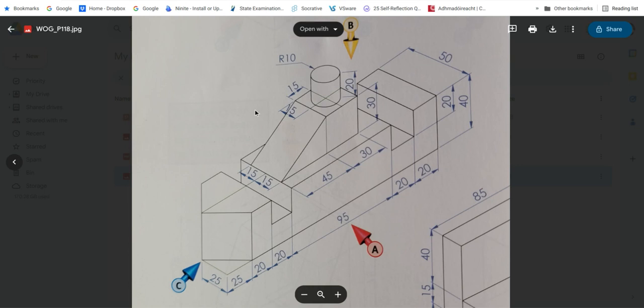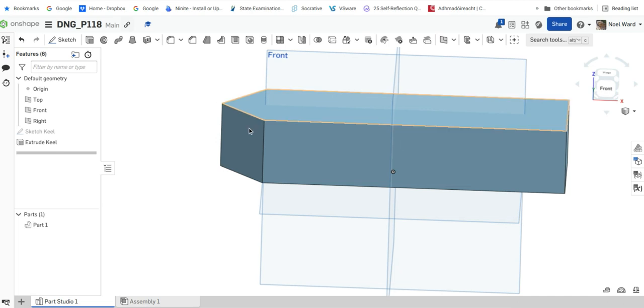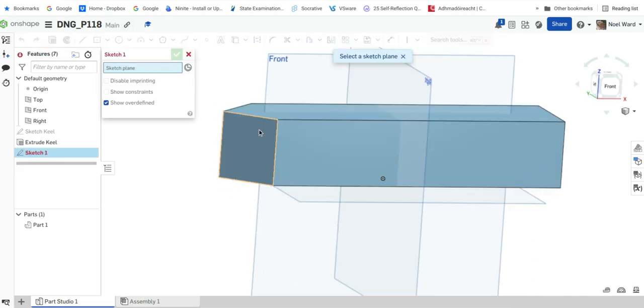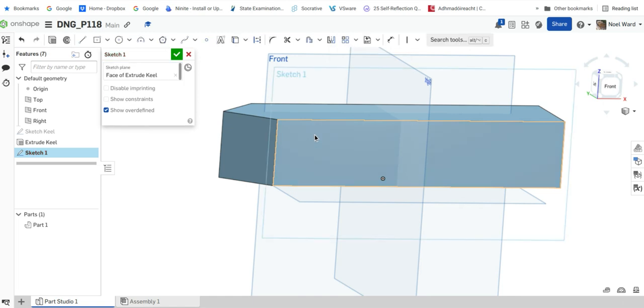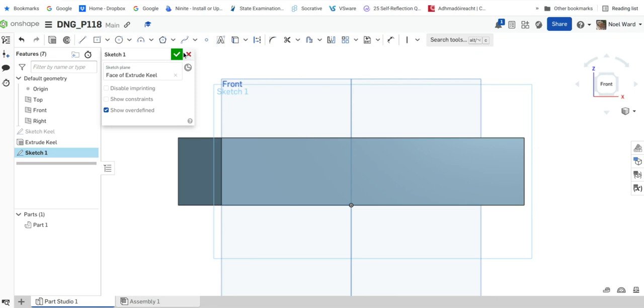Take a look. Then there's a couple of openings here. Simple dimensions, 20 in, and then it's the same 20 in and 20 in from that edge, not from the end of the boat, from the end of the boat the other side. And it comes down to halfway, which is 20. So I'll just show you how we do that there. So I need to go to sketch again, and this time I'm picking the front surface of the boat, the bottom of the boat. Hit the letter N to bring it normal to, and I'll just say cutouts.